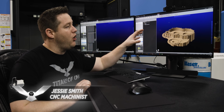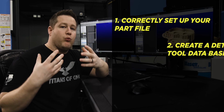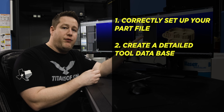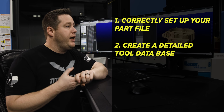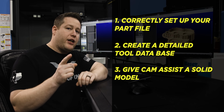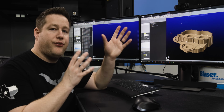Now guys, you can see that I already got the part file open, but before we get started, there's a few things that we need to talk about in order to make CAM Assist successful. There's three major things that you need to do. Number one is to set up your part file correctly. Number two is to create a robust, very detailed tool database, which we spoke about in our previous video. And number three is to give CAM Assist a very good solid model. Now that is the part that we're going to get into a little bit later in the video. So first, let's look at setting up the file.